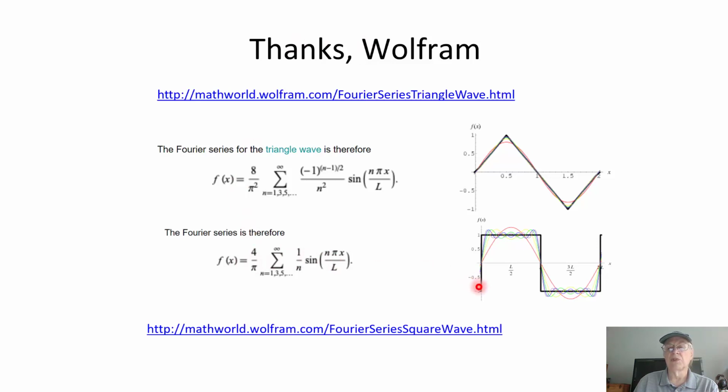Here's a Fourier series that represents a square wave, okay? So the square wave is there in black, and the components that are required to build it are shown in other colors, okay? Actually, I think what they're doing is showing you the sum of these components individually. And it turns out that what you really want is the odd harmonics. So look at the equation here. The function is a sum of the odd harmonics 1, 3, and 5. So we have a basic fundamental wave, maybe 100 hertz. And then we have 3 times that, 300 hertz, 5 times that, 500 hertz, and so on.